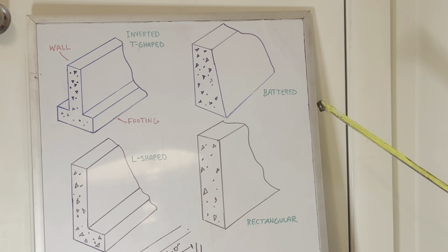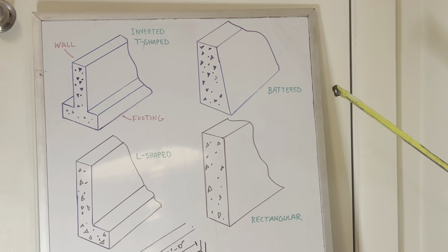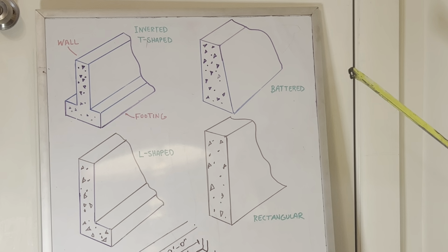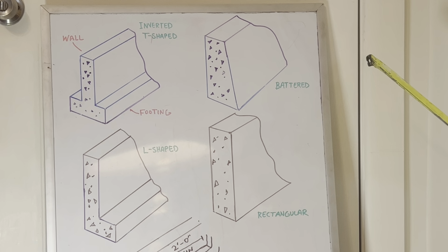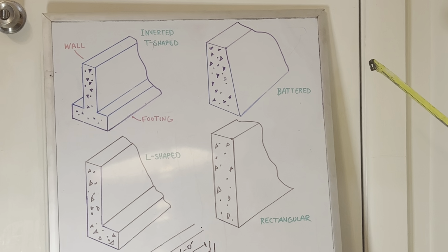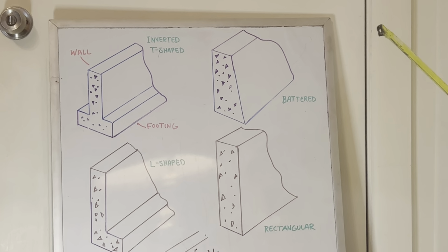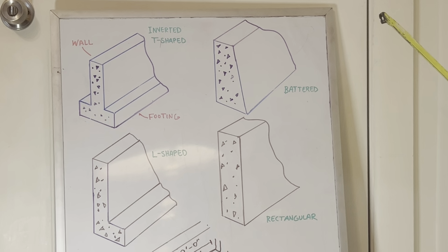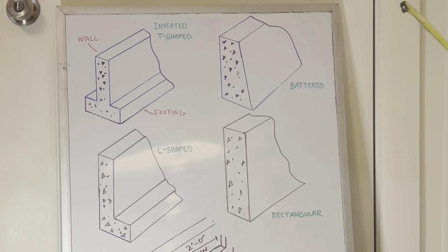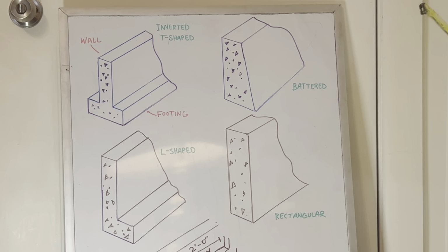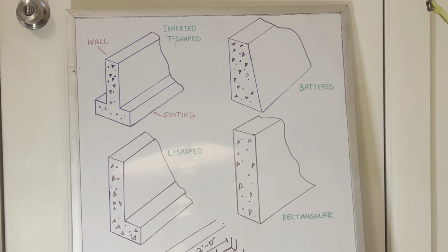Major factors that determine foundation design are the live and dead loads the foundation must support, and the soil conditions. Now, the live load would be people coming in and out of the building. Also, the live load is your furniture and your appliances. The dead load would be the weight of your framing, the components that make up your house. Another example of a live load could possibly be snow accumulated on your roof, because it's going to be temporary. It's not going to be permanent.